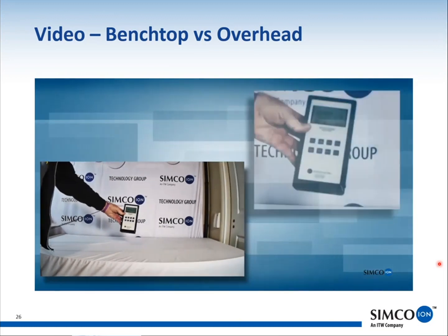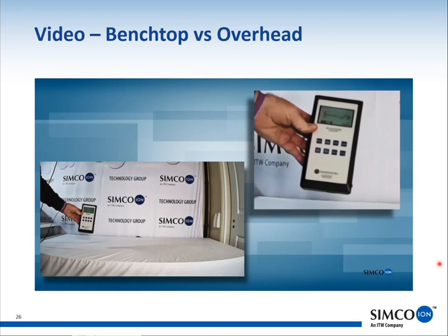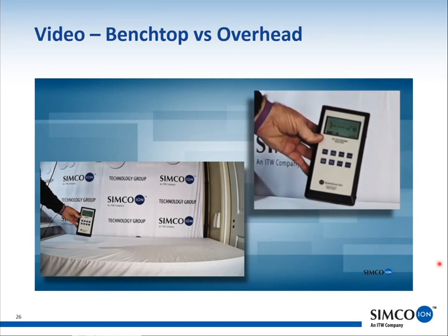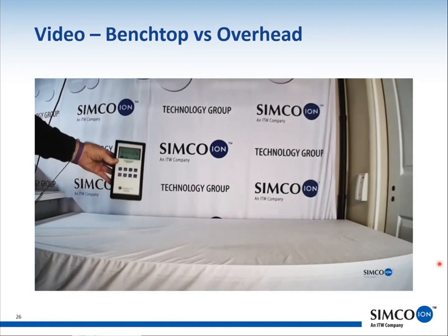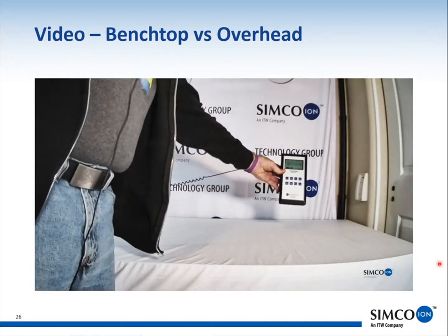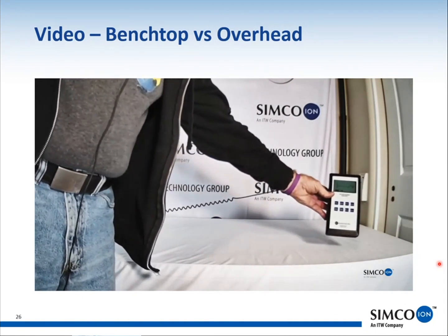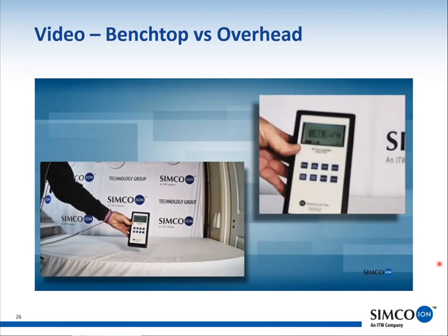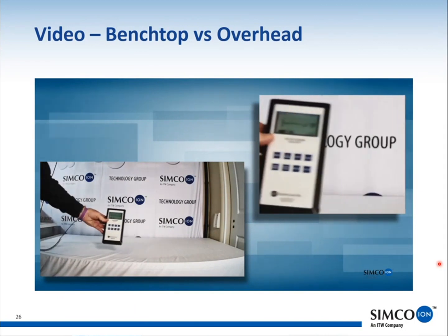And as you can see, when I'm centered underneath the fans, I maximize the meter, well over 200 million ions per cubic centimeter. I'm only looking at the positive ions because, again, it's a balanced blower, so there shouldn't be any difference. And even as I move towards the front of the bench, I still have a maximum number. It drops as I go in between the fans, but then it goes right back to pretty much maximizing it.